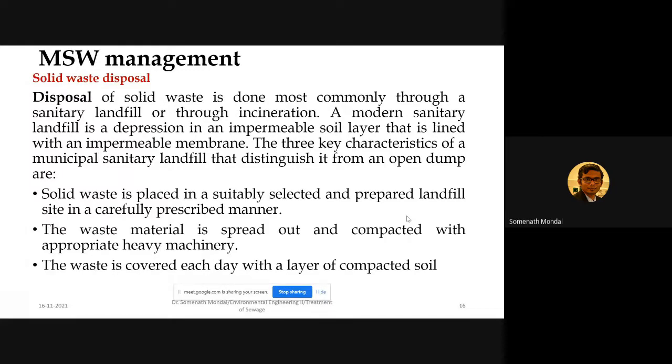Next, we have incineration. So basically, this is a controlled burning of the waste at higher temperatures. So this is 1200 to 1500 degrees centigrade you apply, and then you have gasification, you have pyrolysis. So pyrolysis is basically the degradation of carbonaceous material to gaseous, liquid, or solid forms, and pyrolysis happens in the absence of oxygen. So that's the main difference with incineration.